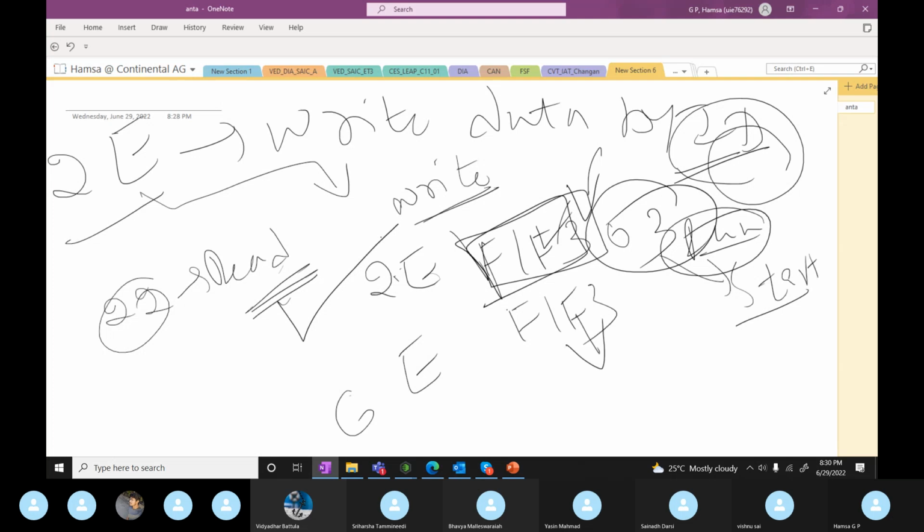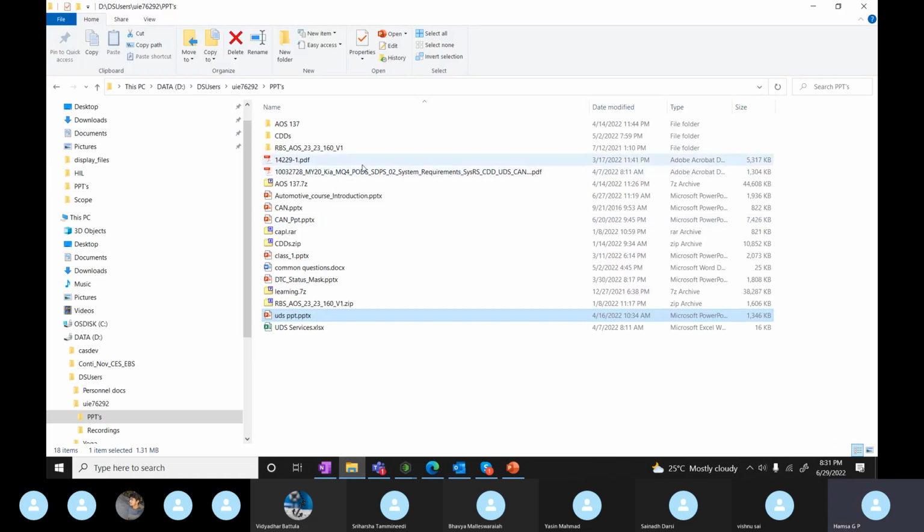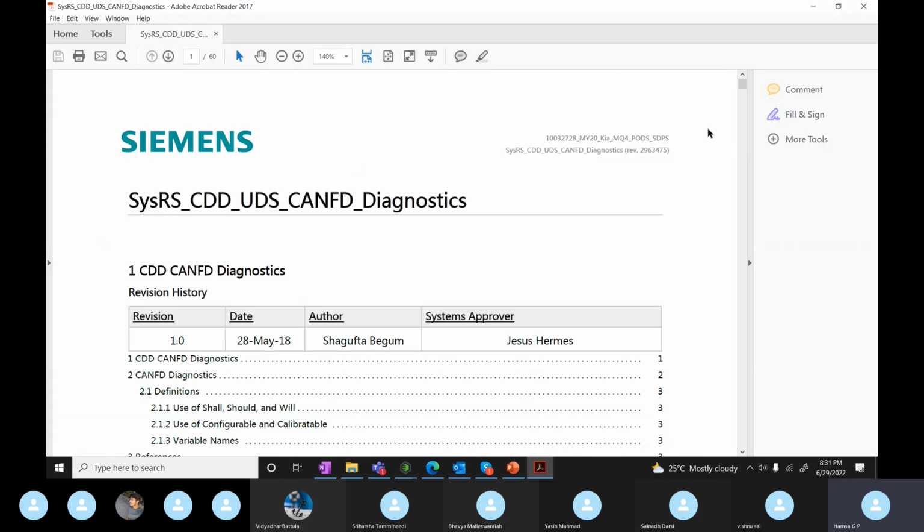Okay. So read and write data by identifier, and then which one did we discuss? 28, communication control. So all these three are clear, and I can show you practically how it looks. In one project you will have nearly 25 to 30 DIDs.